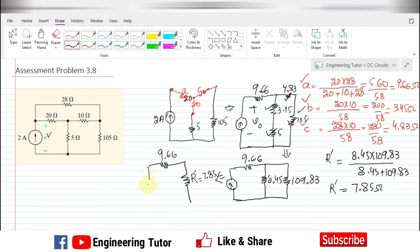And the source connected with this one is again 2 amperes. Simplifying again, because now 9.66 and 7.85 are in series with each other, this will give me an equivalent resistance R equivalent. This will be the summation of 9.66 and 7.85, so it will be 17.51. Okay, and the source current is 2 amperes.